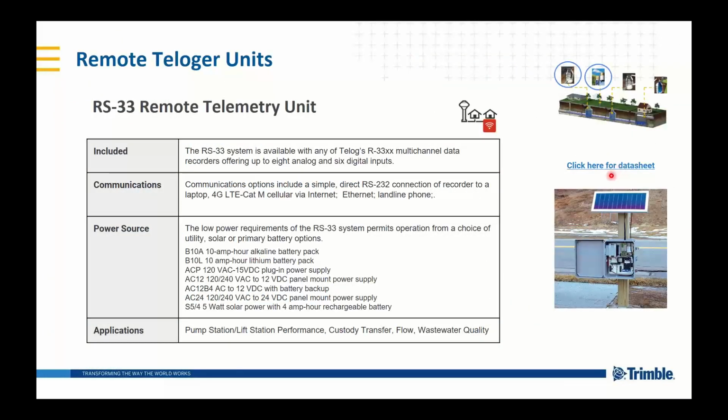So here's what our RS systems are. They're multi-channel data recording, and they can take up to 8 analog or 6 digital inputs. That's for our 14 series. We can communicate with RS-232 through a cable. It can also communicate with 4G LTE via the internet, and we also have the ability to communicate through an Ethernet or a landline if they're still out there. They have very low power consumption and requirements, so we can have a backup with solar as well, or some external batteries. And here's some of the power sources that we have available.